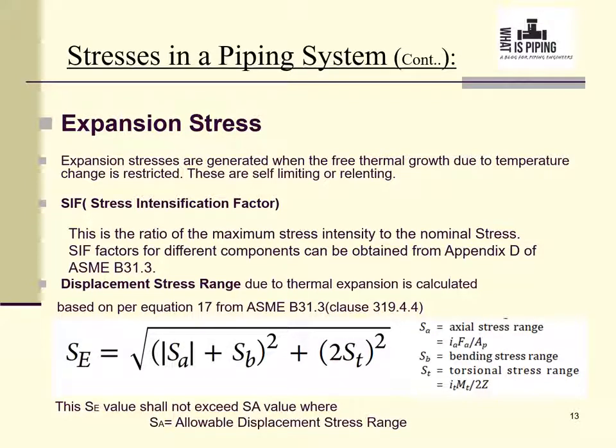Now SIF, that is stress intensification factor: due to change in geometry or in cross-sectional area of the piping systems, stresses are intensified at various locations. The stress intensification factor is defined as the ratio of the maximum stress intensity to the nominal stress. Code